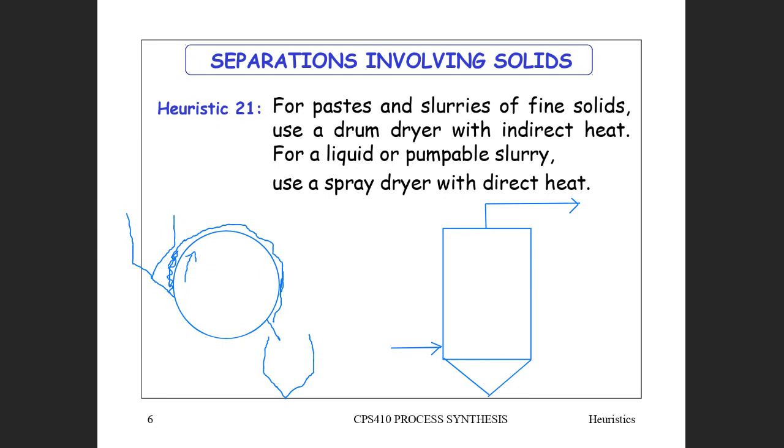We've also got, let's go for a different color, our stuff, our slurry coming in over here and being pumped in. And there's a very specialized spray. And this is the secret of unit operation design here, is there's a spray ball that makes droplets of exactly the same size, because usually your coffee granules, you want to have all of your granules about the same size.